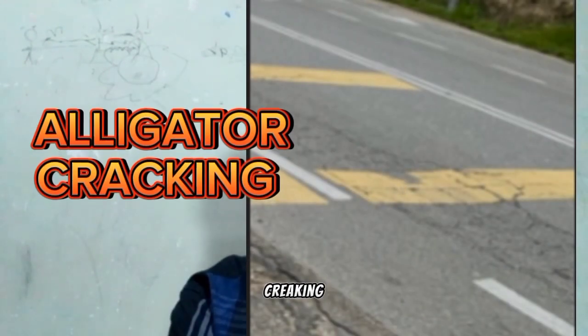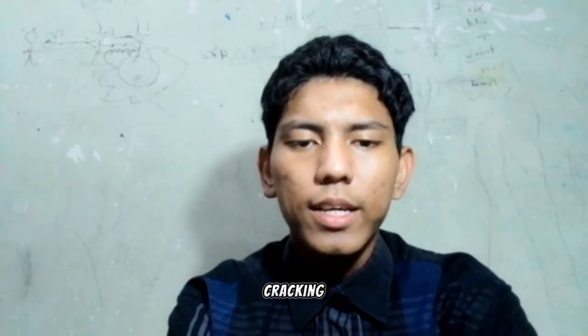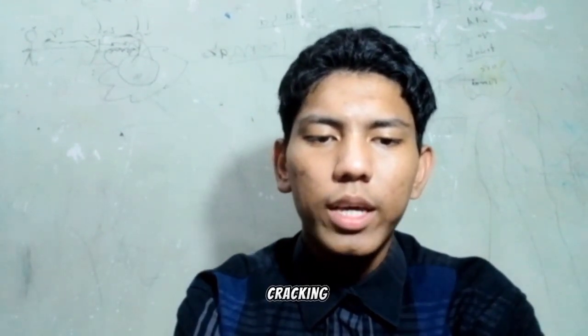And the second picture is alligator cracking. As you know, alligator cracking is a load associated structural failure, and the failure can be due to weakness in the surface, base or subgrade, a surface or base that is too thin, poor drainage, or the combination of all three. It often starts in the wheel path as longitudinal cracking and ends up as alligator cracking after severe distress.